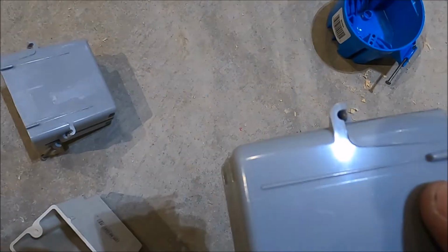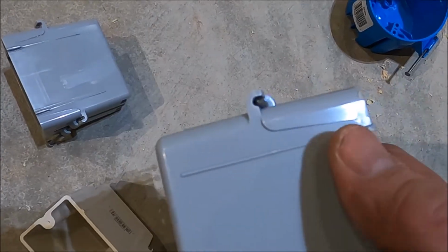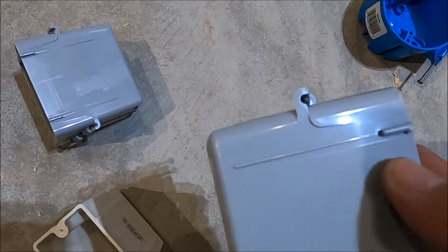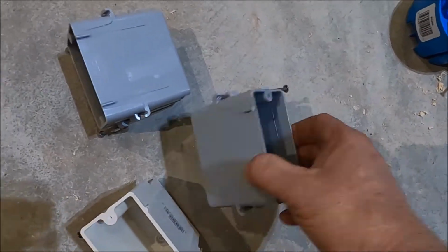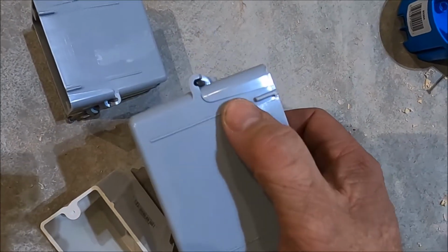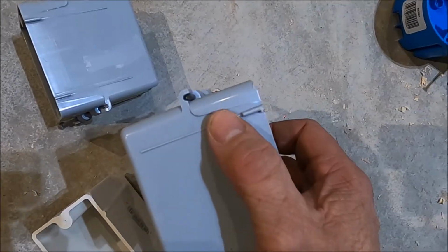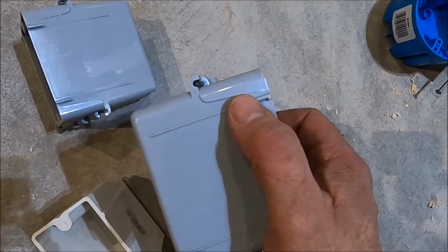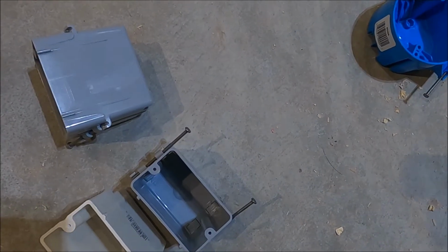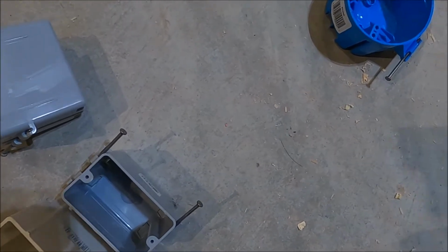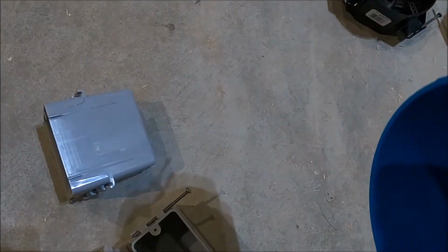The main thing is there are these little tabs that you want to make sure sit against the stud, because that gives you your setback for your drywall. So if you leave like 1/4 inch or something between the stud and this little tab, then that box is going to stick out and you're going to have a heck of a time trying to get everything to look right when you get your outlet or switch in place.